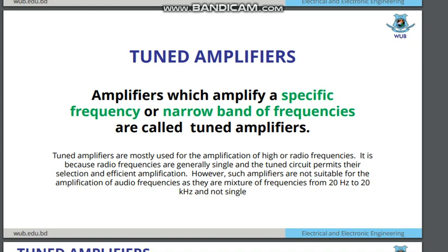It is because radio frequencies are generally single, and the tuned circuit permits their selection and efficient amplification. However, such amplifiers are not suitable for the amplification of audio frequencies, as they are a mixture of frequencies from 20 Hz to 20 kHz and not single.